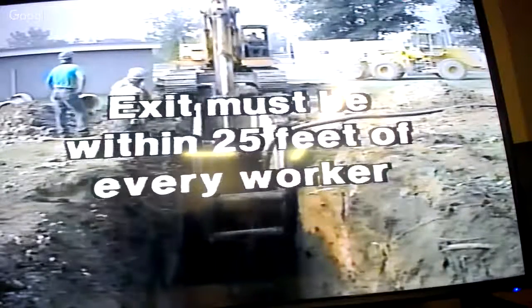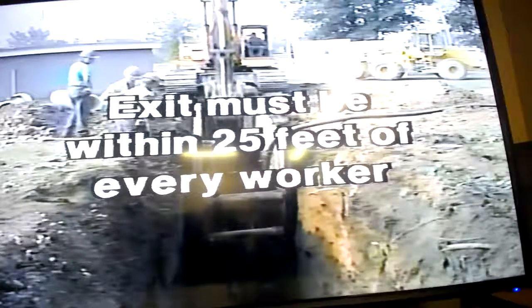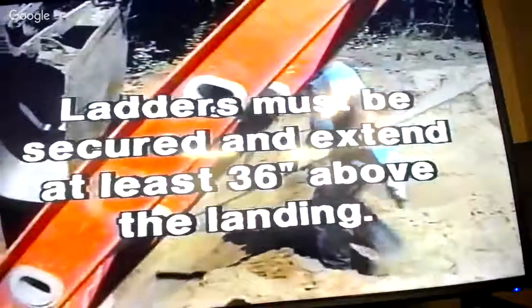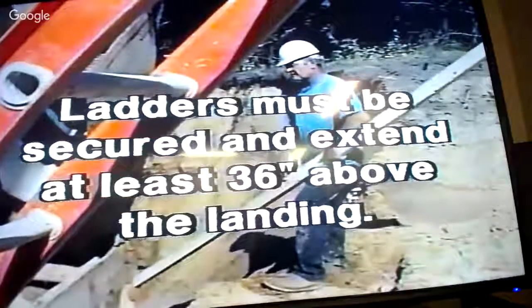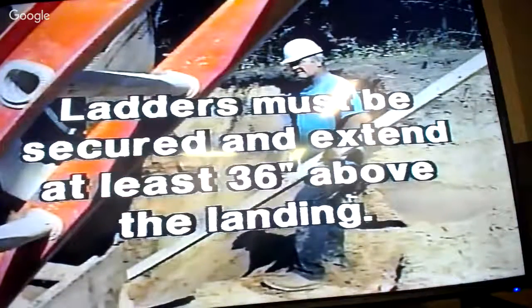The exit must be within 25 feet of every worker in the trench. Common types of exits include a stairway, ramp, or ladder. If used, the ladder must be secured and extend at least 36 inches above the landing.